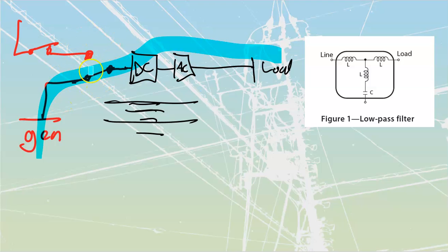The generator and the generator transfer switch, they don't need to interface with the UPS other than that they're feeding power out. The generator is always going to be upstream of that UPS on our critical types of systems. Good quality UPSs are going to have a good set of reactors inside of them. In a lot of cases, they're going to have transformers as well that are also going to give us further filtering out of them.